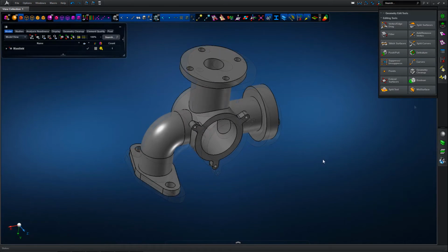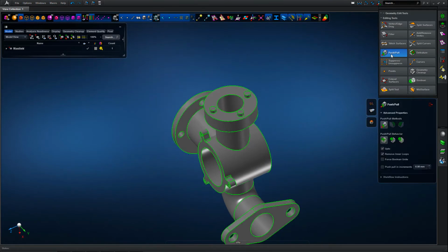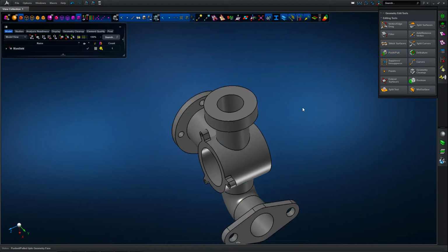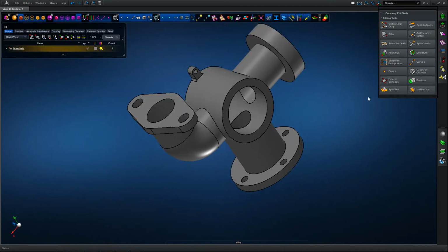So taking out the chamfers as well, we've now got a much simpler form. We've got some locating spigots on one of the faces, so we're going to remove those just by a simple push pull up to operation to smooth them off with the underlying face. And now we're in a position where we can start to understand how the geometry will work from a hex